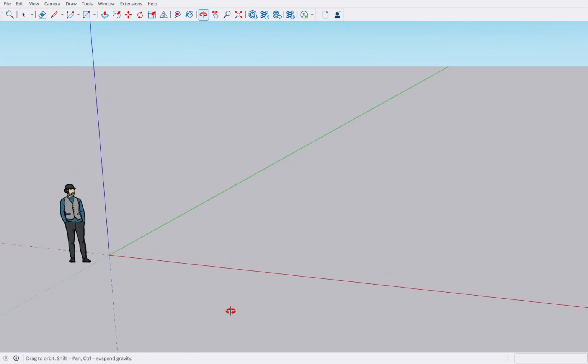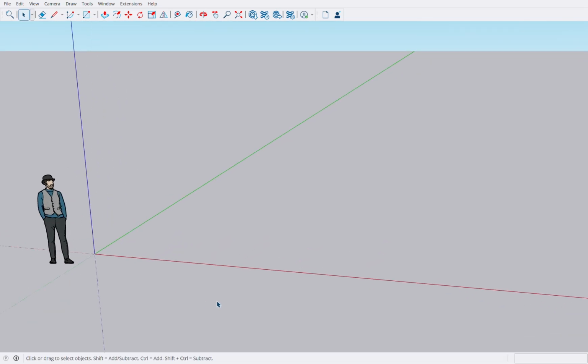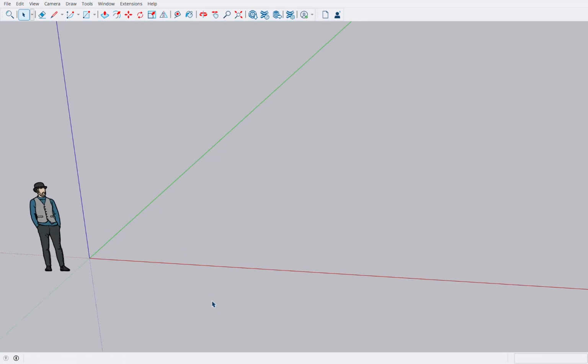So to demonstrate this video, first off we're just going to build a simple house, and if it's your first time in Sketchup, the easiest way to build a simple structure is we're going to go up to our toolbar at the top and we're going to select our square. Now, what you can do is click and drag and enter on your keyboard 10 feet, comma, 10 feet. It will show up in your bottom right corner.